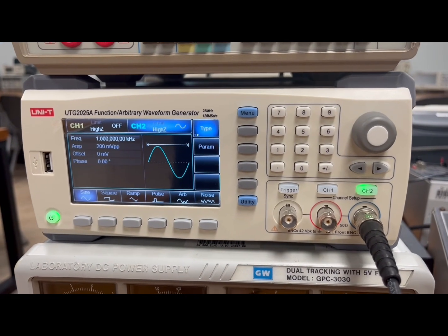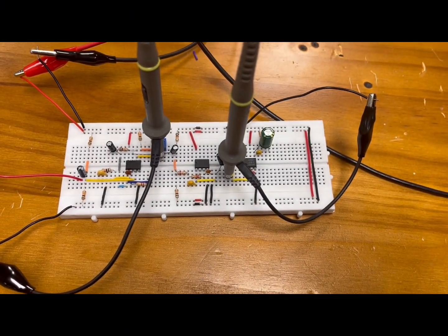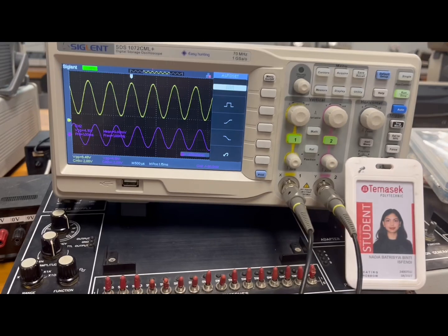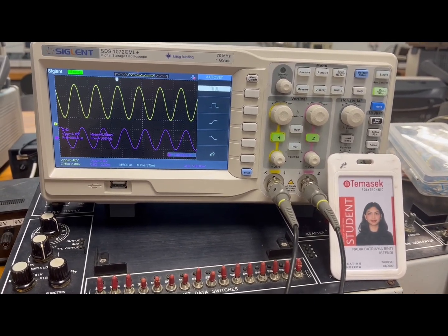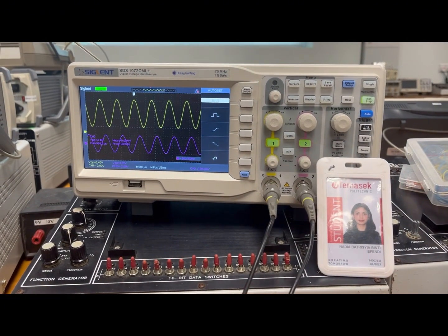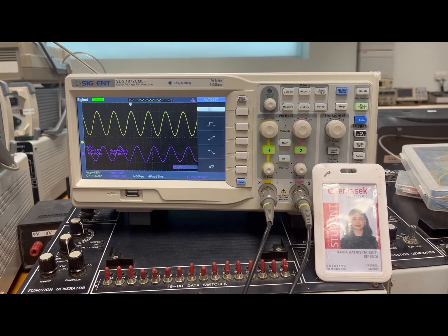At 1 kHz, keep TP3 at channel 1 and place channel 2's probe at TP4 and get a filtered output voltage of 4.15 volts. Since unity gain is not applicable as the frequency is above 500 Hz, there is a drop of output voltage from TP3 to TP4. The output waveform at TP4 will be determined by the output at TP3. Hence, by adjusting the trimmer at TP2, it can also control the output at TP4.